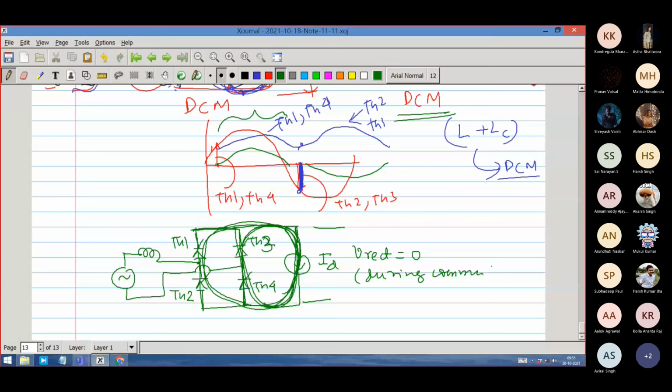Right? This is the difference. We'll give a more analytical treatment for the 3-phase case. You can yourself do it. It is not so difficult. It is a sine wave. You are fired at this point. So here, this is the zone where this bridge is shorted. And the bridge being shorted means what is the equation? At this instant it has been fired. So this value is alpha. So you will write LC di by dt during the commutation is equal to Vm sine alpha.